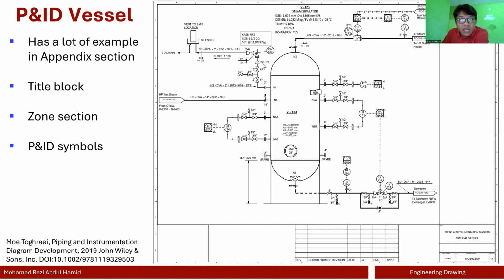Okay, on this side, these are quite important. These are called a pressure safety valve or pressure relief valve, whatever. It's to safeguard or to make sure that your vessel is not getting destroyed in the case of overpressure, where in this case they use a fire case. Let's say there's a fire, right? And then maybe the temperature on the outside is so high that it leads to a pressure increase, to a point where it is above the design pressure of 11 atm. Without this, it may blow up, or it will break or rupture or whatever.